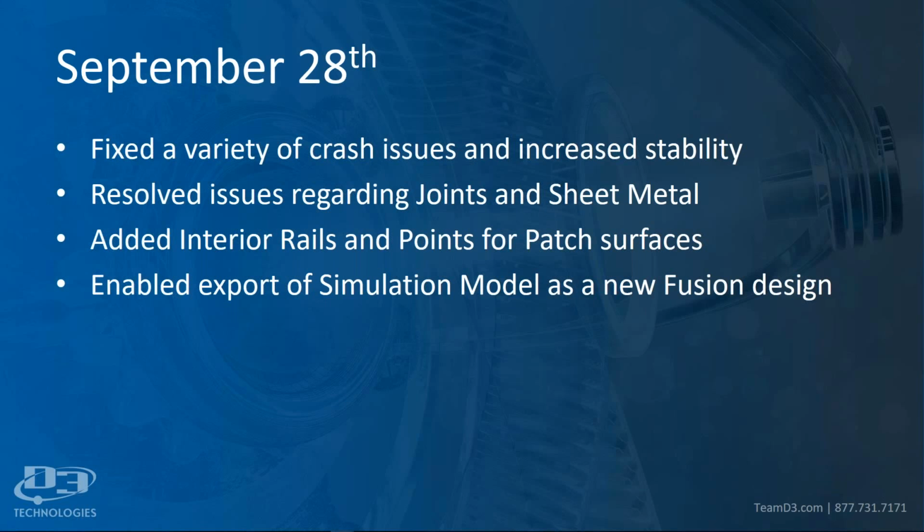It can really be crazy unless you have some pretty good training on it. My early days in the patch environment got, let's say, explosive. You delete one thing and you don't know that you just opened up, for example, a 5-star patch that was generated in that particular spot. It was actually a couple of triangles, basically a triangle and a square, and you deleted those, and then you try to put in the 5-star patch, and you get your order of operations wrong, stuff like that.